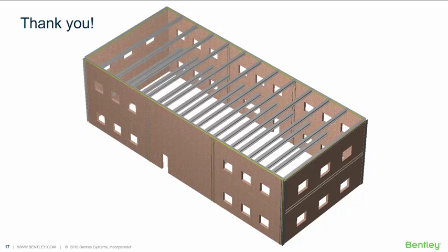But that being said, this is a little more friendly to do in RAM Elements. Yes, and today's topic is masonry, but as you may know, RAM Elements also has a concrete wall module. If you're designing shear walls in that one, the software allows you to specify boundary elements, whether as flange perpendicular walls at the end, or as columns.